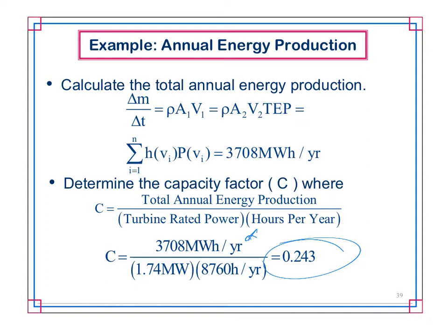So for renewable energy, they tend to have a fairly low capacity factor because when is the wind blowing at 15 or 14 meters per second? If it's in a steady offshore application, okay, maybe you have higher capacity factors, but onshore they tend to vary quite a bit. So that's why we want to locate stuff not only where we have high wind speeds, high average wind speeds, but consistently high average wind speeds.